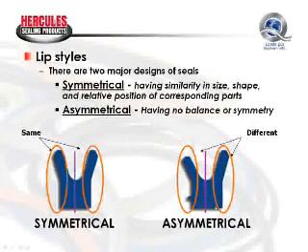Another seal lip configuration worked better for sealing in a static application. By combining the two different types of lips in one seal, you had a better performing rod seal or a better performing piston seal. So they were able to improve seal performance in low pressure dynamic sealing applications.